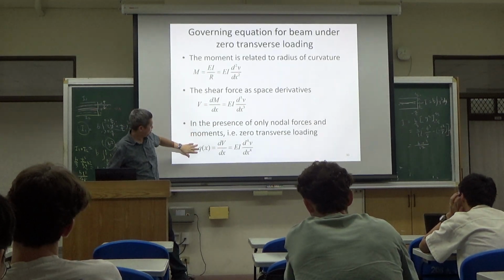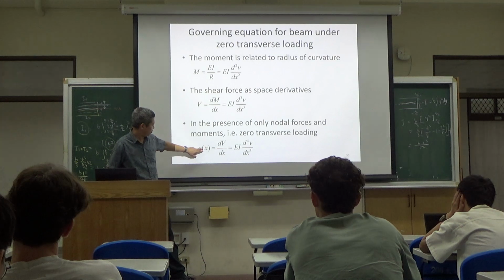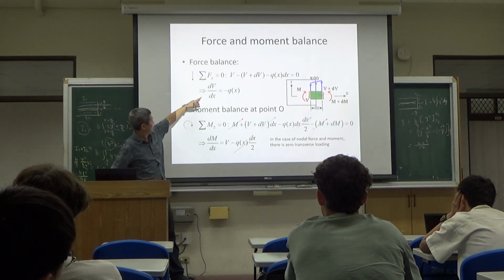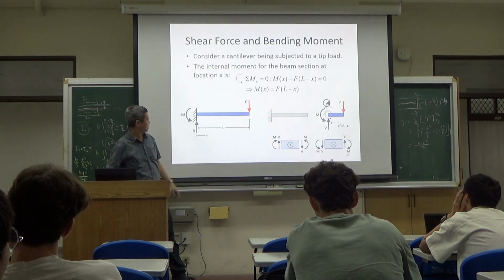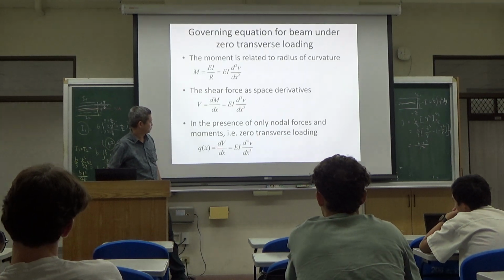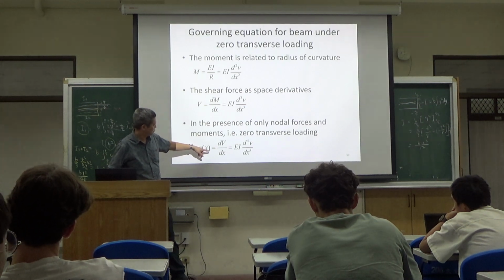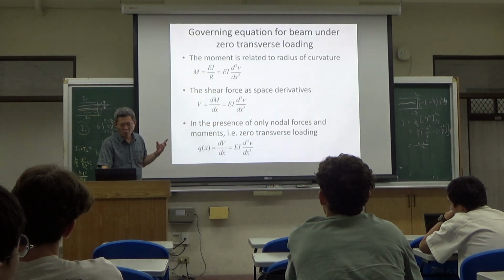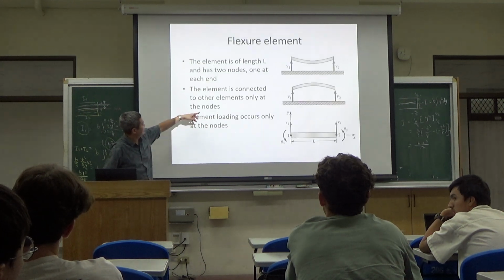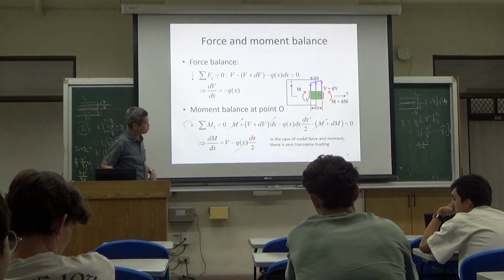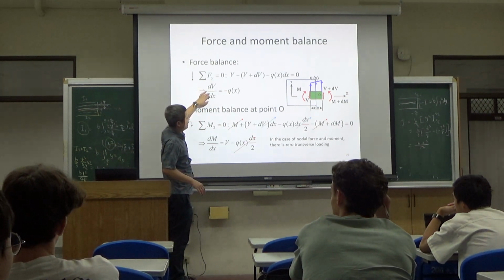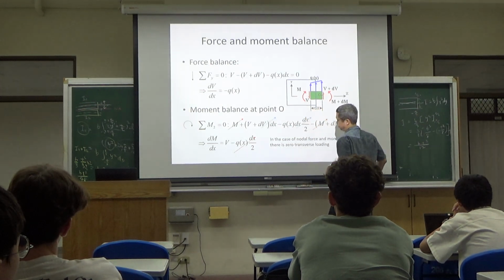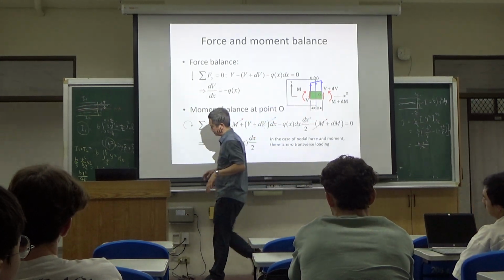And then how about the distributed force? The distributed force, as we derived from the beam bending theory, is dV/dx. So here, they already have the change of convention, depending on what you take to be positive. So the dV/dx here, let's see. Okay, let me draw this out.